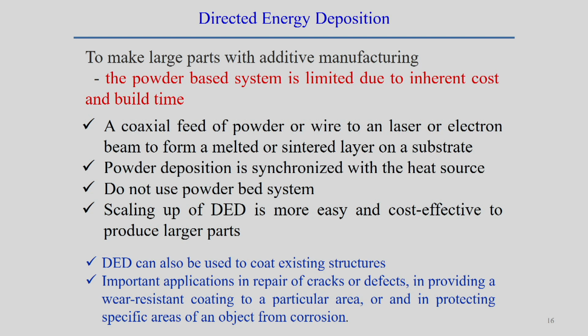Once a layer is formed, we need to spread the powder for the next layer, and after that we need to level that particular thickness of powder material. After that we can focus the laser beam on this powder to create the shape of the object by following this particular path. That is why it is normally time consuming and involves a large amount of raw materials in this case.